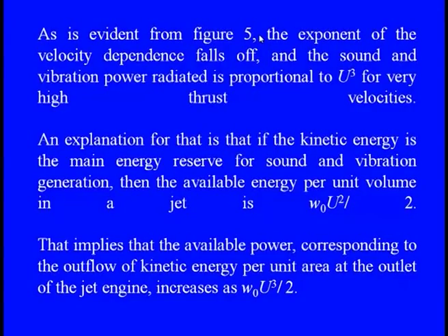And if we go back to the basic theory, that if the kinetic energy is the main energy reserve for this vibration or the sound generation, then the available energy per unit volume for any kind of jet is W0 u square by 2, because when we apply this theory, this gives the available power.